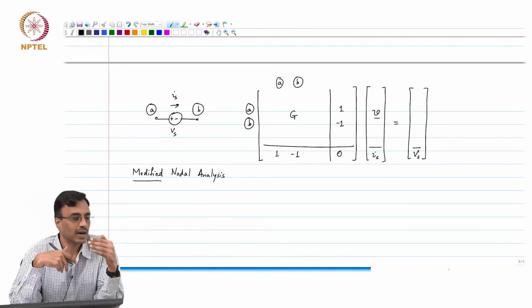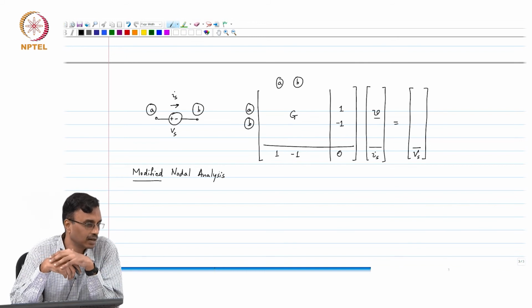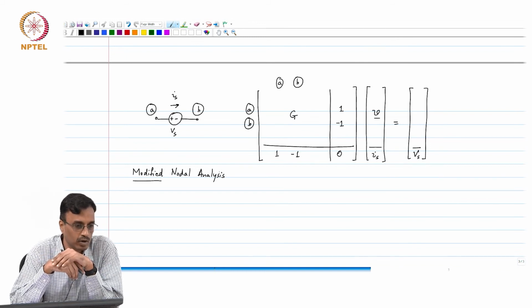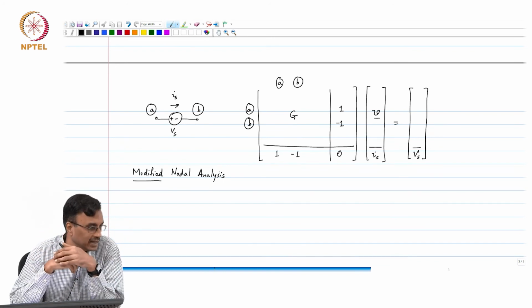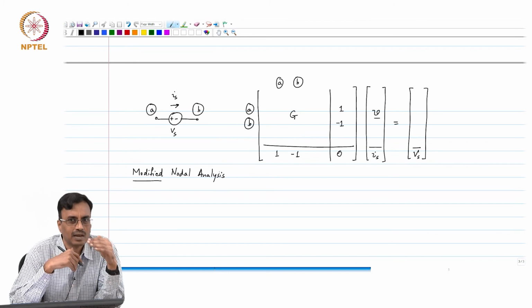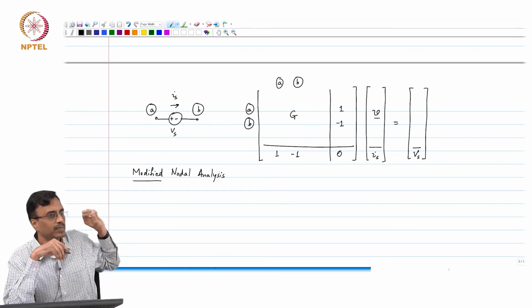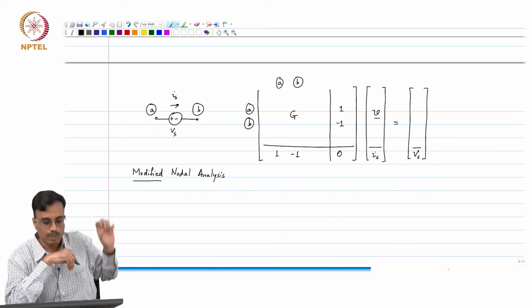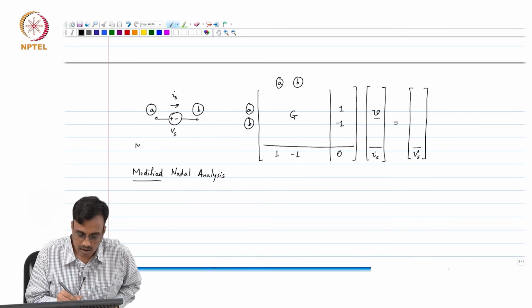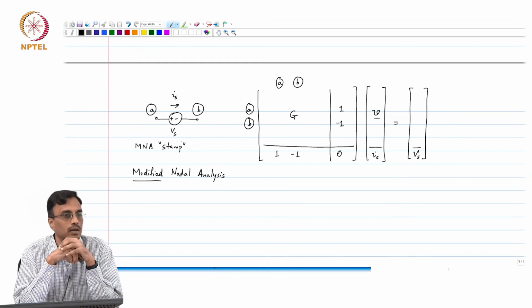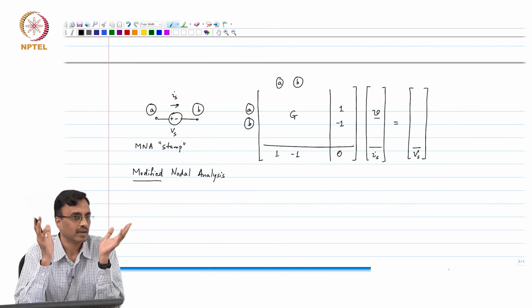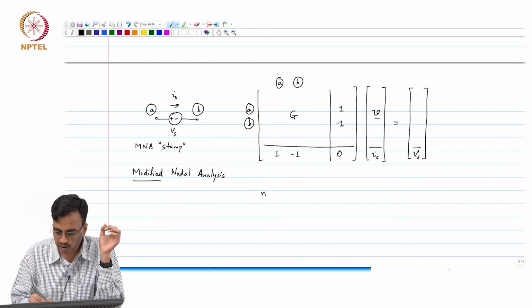You just describe the netlist, and in a computer, you have a parser which takes a circuit diagram that you draw and generates a SPICE netlist, and you keep going line by line in that netlist, and you look at the element and you can simply plop its respective MNA stamp, as it is called, into the matrix.